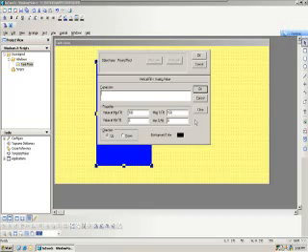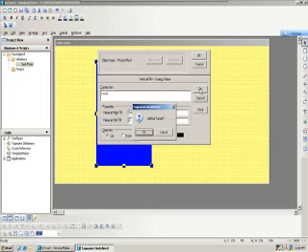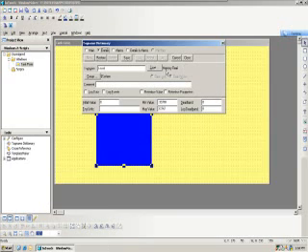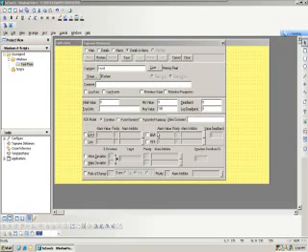So what's going to drive this animation? It's going to be a tag called level. This tag does not exist because this is a new InTouch application, so we'll go and define it. We'll tell it a type, what group, give it a min value, 0, maximum of 100. Now these are the essentials for the tag. We do have the options of putting in much more detailed configuration, but we'll leave that for another video.